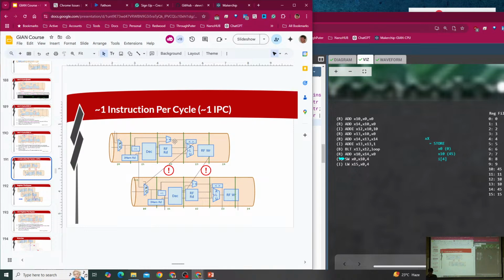So potentially, we could do this path a little earlier, right? We can do the offset calculation in the stage before. Potentially, we could drive that offset calculation to the PC mux. We already know whether we're a jump or not. We're not going to do that optimization. We'll just do it the same way that we did branches. If you'd like to try that optimization, feel free.